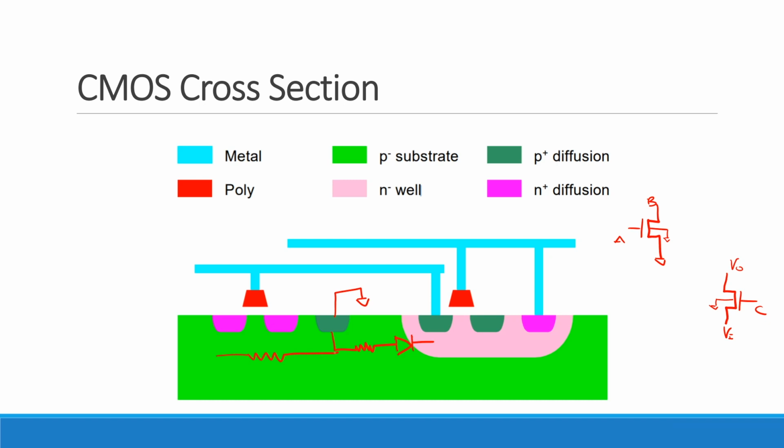So every time you put a PMOS, usually again in SPICE, you just do something like, okay, I've got my 4 terminals, right? But in fact, there's almost always some diode sitting there, basically from the body to the substrate, right? Actually, I guess I drew that the wrong way, but you can figure that out. So every time you instantiate a PMOS, there's actually extra stuff sitting there that SPICE is never going to handle. So the point here is just to pay attention, because sometimes that extra stuff actually is going to matter for the circuits that you're going to build.